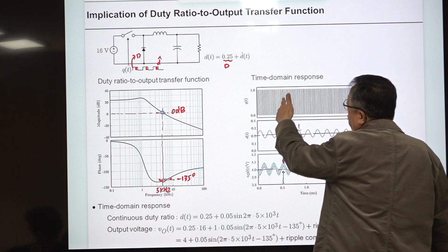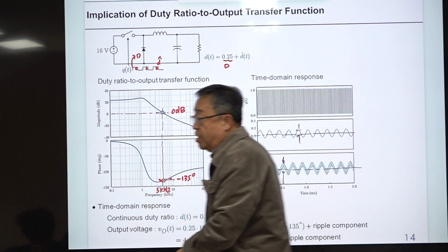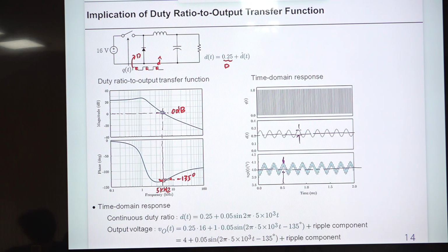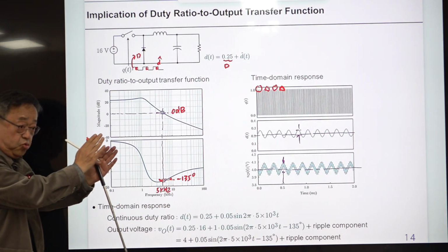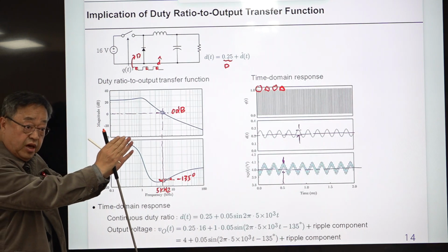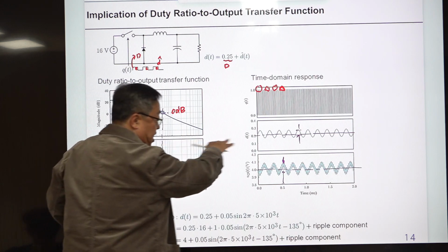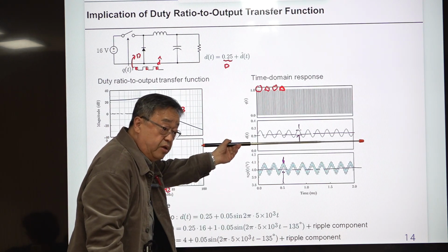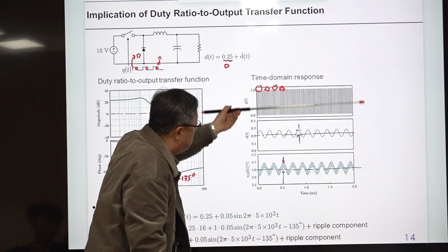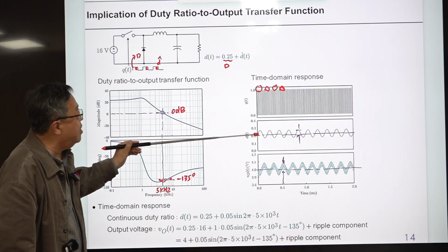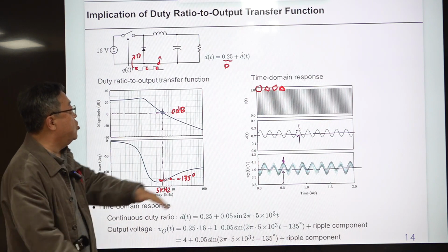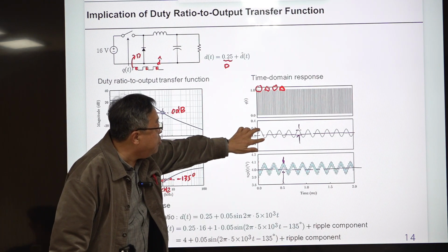All right. And here, this is fixed, and the duty ratio is here. But if you take a close look at this, the on-time period will be changing. You cannot see this here, but the on-time period is large here and small here, large here, small here, and the variation is sinusoidal, something like this. So this duty ratio is increasing and decreasing in sinusoidal fashion in time domain. I generated this using some simple circuit, so I was able to generate this switch drive signal whose duty ratio is changing in sinusoidal fashion